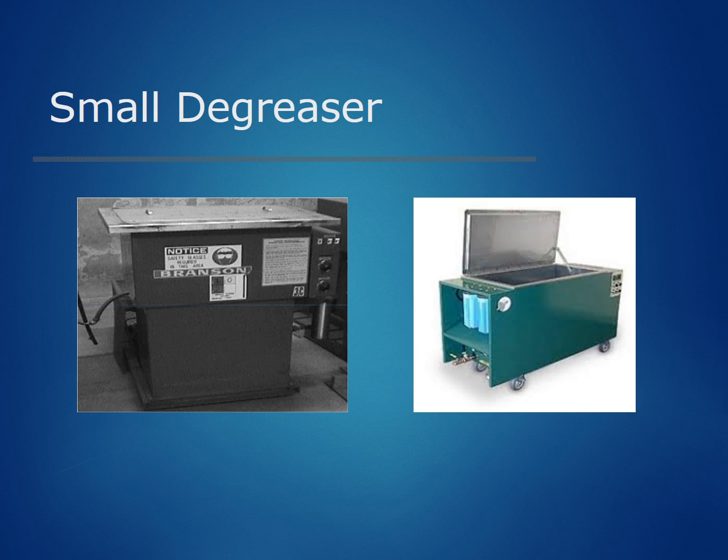It should be a standard operating procedure to keep the lids of these units closed when not in use to prevent solvent vapors from escaping into the workplace. However, in most shops you will see them left open. This is just a poor practice and creates potential solvent exposures for all the workers in the shop.